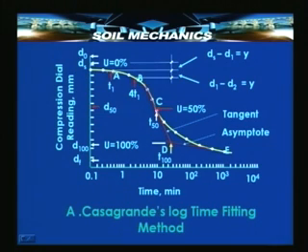So, assuming this to be a parabola, we will try to find out the corrected starting point ds, that is the point corresponding to 0% consolidation. We will also then find out the point corresponding to 100% consolidation, and 50% consolidation will be in the middle of this range, and from that we will be able to get small t50 corresponding to capital U50. Once we know small t50, again we use the same formula involving CV and get the value of CV.